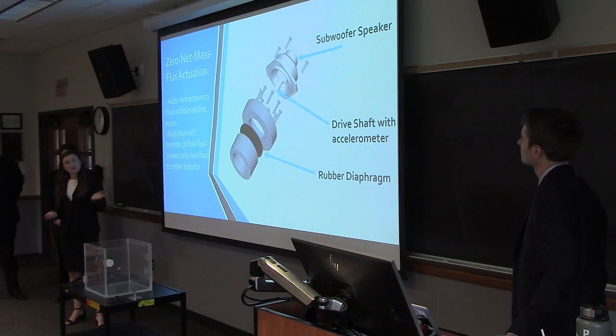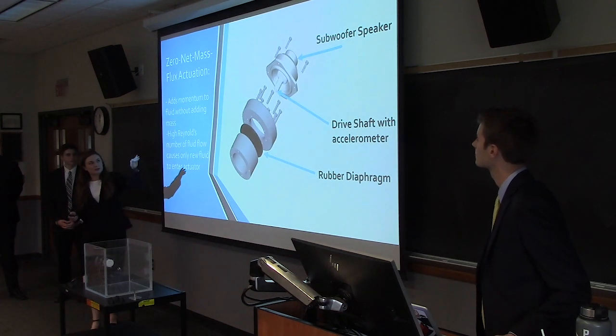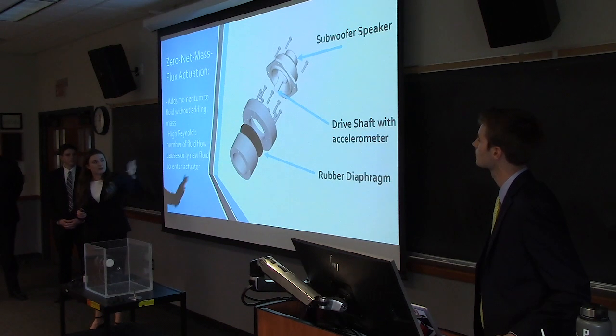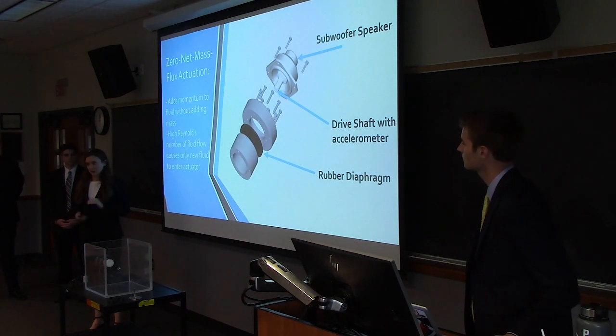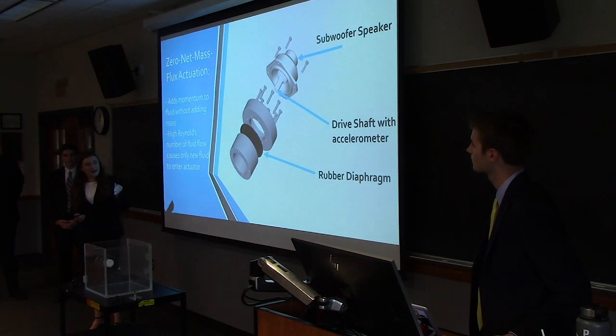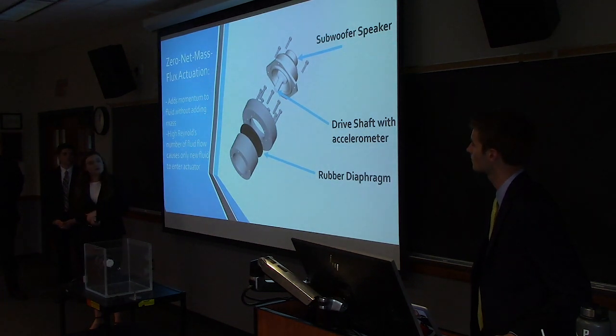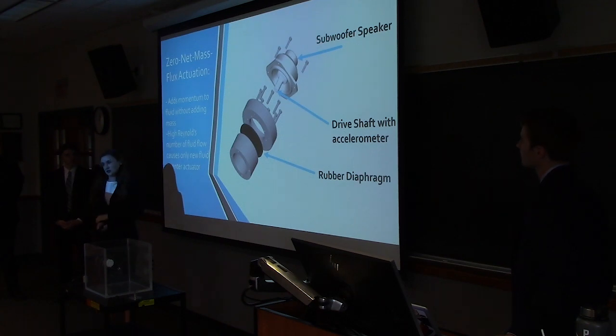Now the basic principle of how the water is pushed through the tank is called zero net mass flux actuation. That's a really complicated term, but in simple ways it just provides so much force from the speaker that it shoots the water through the orifice holes into the tank like shrapnel. So it shoots out so quickly that the same water is not allowed to return back in. Different water from the tank comes back in. This adds momentum to the fluid without adding any mass to the system. So there is a zero net change in mass of this entire system.